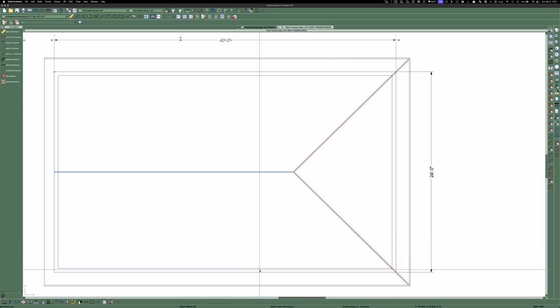If you are running joists, the actual span for a joist is where it's no longer supported, and that would be on the inside to inside. And when I started down in Texas, we had 3.5-inch walls. A lot of times, if you're familiar with framing, there's a bird's mouth with a plumb cut and a seat cut.